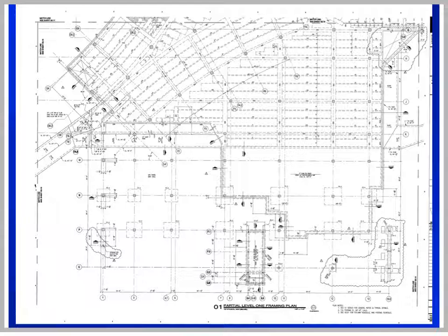And here is another engineer's partial level framing plan where we see both foundations and elevated structures being delineated. Let's zoom in a little bit. And we can see here an interesting way of making section numbers instead of the typical little round circle. They just put an arrow pointing to it.